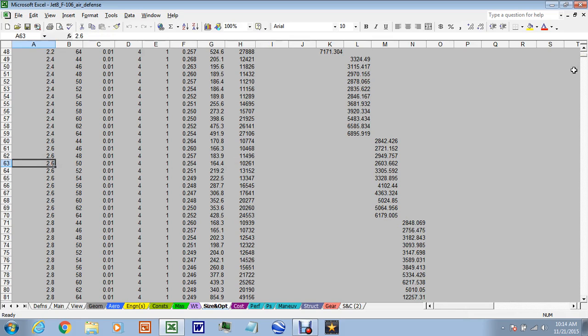Now in theory, because this is a solution to the sizing equation, if we size the whole aircraft down with this shape wing, it would be the optimum and it would only weigh 10,000 pounds. But of course we can't do that because we can't size the fuselage down. The fuselage has to carry the weapons and the pilot and the fuel and everything. And so when we size the aircraft down, we can't actually achieve this 10,000 pound takeoff gross weight.